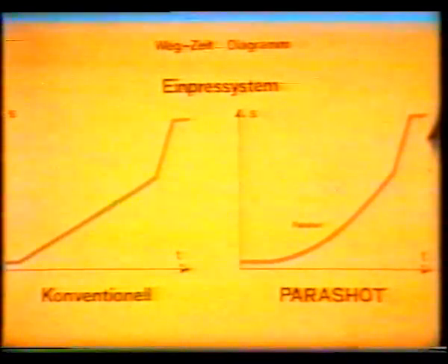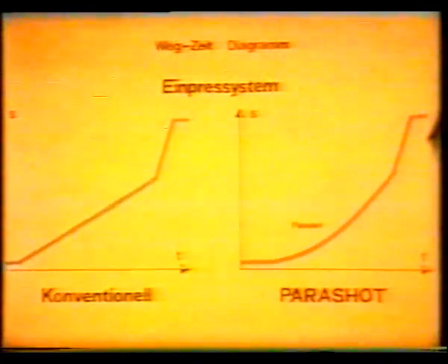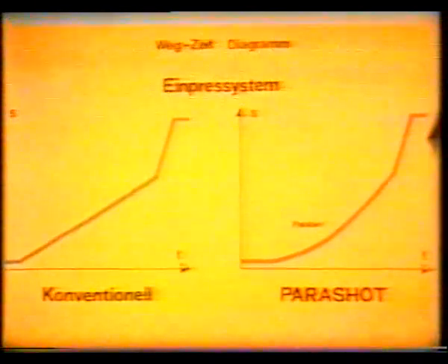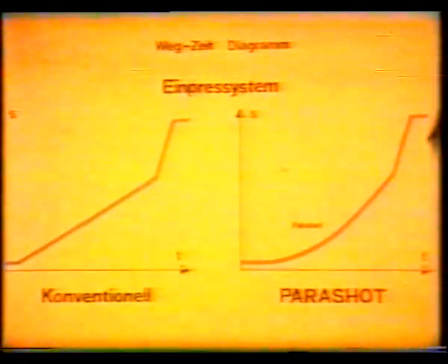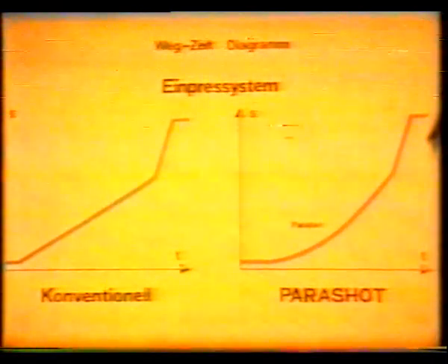Some very promising aspects of this system will bring about many advantages for the die caster concerning quality, optimum surface finish, homogeneous structure, minimum dispersion of strength values, higher filling ratio, and, as a result, economical production of die castings.